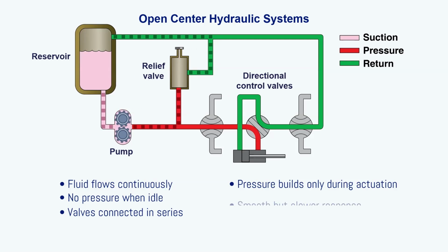One advantage of the open-center system is that it is not continuously pressurized. Pressure builds gradually, which reduces shock and minimizes pressure surges. However, because pressure must build after activation, the system operates slightly slower than other designs.